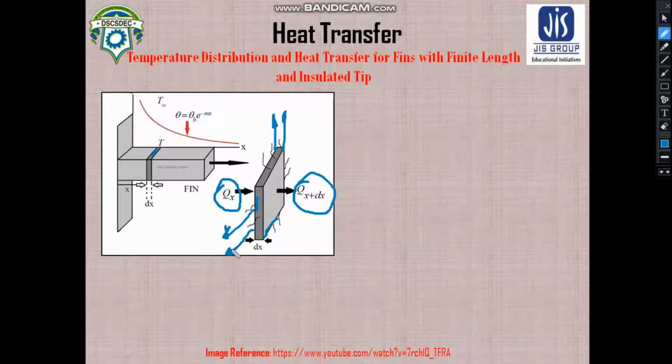So heat transfer is taking place through the mode of convection in four directions: in this direction, the direction opposite to this plane that is hidden over here, and again heat is getting transferred via convection from this plane and the plane opposite to this. So you can see the net surface area of convection heat transfer is getting increased hugely, so that increases the heat transfer rate. So this is the working principle of any fin.